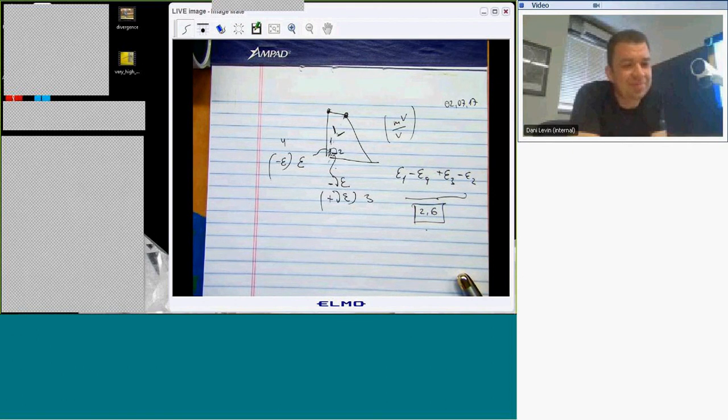Sampling rate? Well, I'm just discovering the instrument that they have downstairs. We'll have enough sampling rate. But normally, usually you want to sample at least twice the dominant frequency. This is the Nyquist ratio.